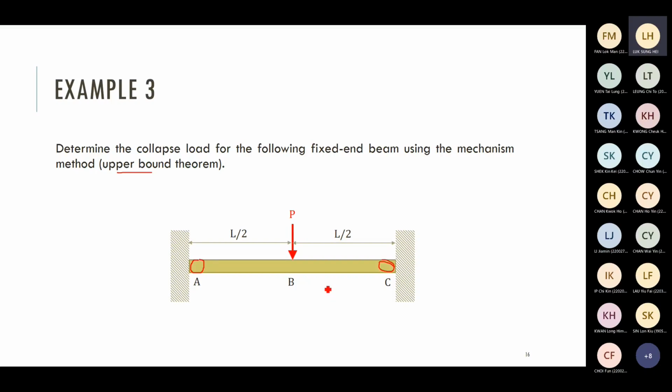After adding two hinges, just like a simply supported beam, then you can add one more. Insert one more hinge, maybe at point B. At this time, you see this unstable mechanism. It seems that the beam may have a large deflection when the load increases a little. You may see this kind of large deflection bending.